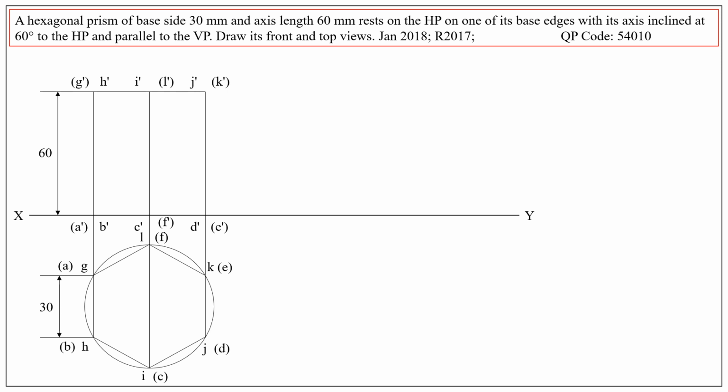But the size and the geometry of the front view of the assumed position and the actual position are the same, only their orientation is different. Therefore, if we reorient the front view to the required angle, that gives the final front view, that means the front view corresponding to the position given in the problem statement.